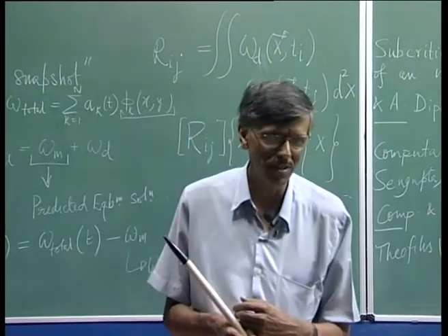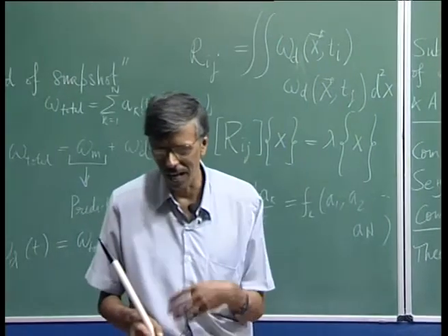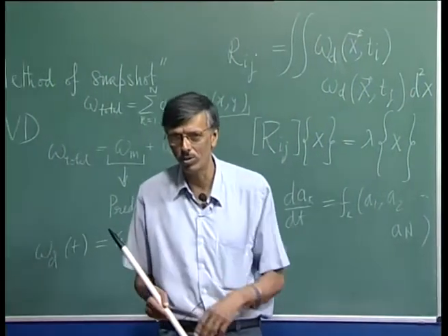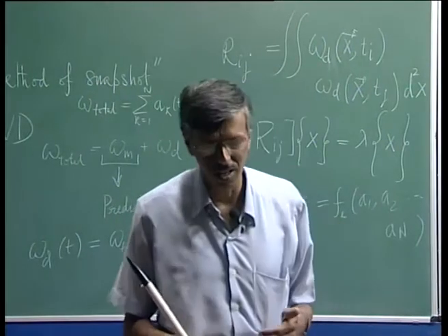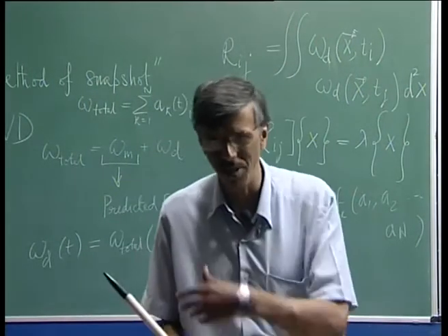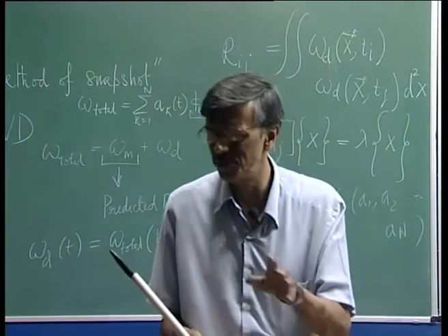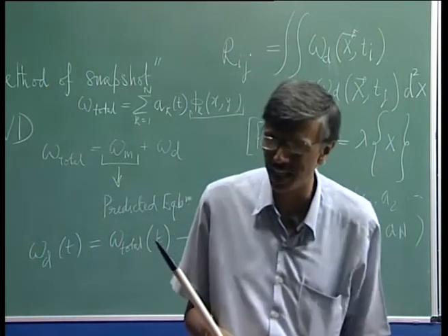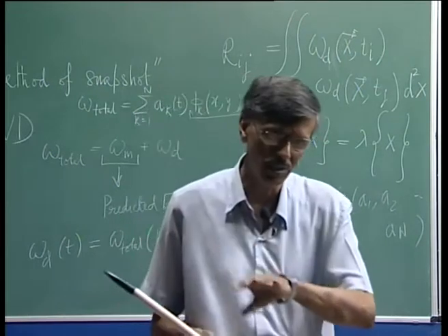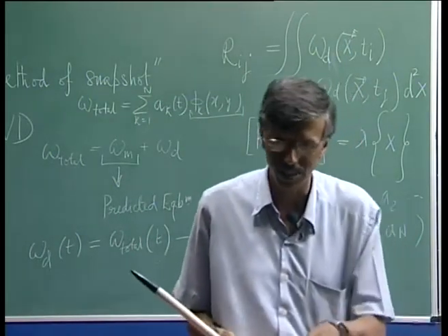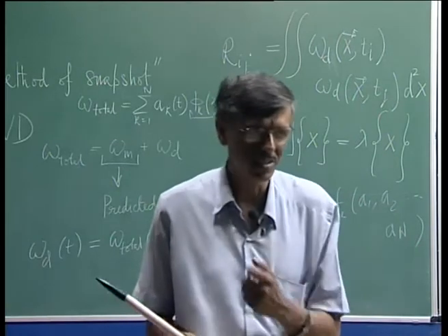And this was a very, very confusing thing. Time permitting, we will come back and talk about streamwise and cross flow instability of three-dimensional flows past a wing. People have now gotten some understanding of what causes three-dimensional flow to be qualitatively different from two-dimensional flows in showing these instabilities.